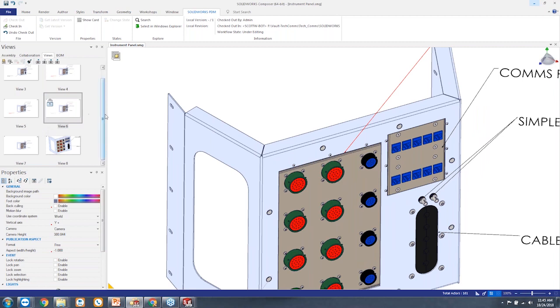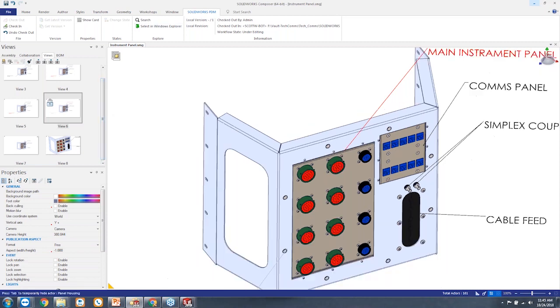But that view now is locked in stone, which is great, because let's say that you change all the colors and reposition things, set your neutral properties, and you're like, this is my view that I want to control after I do an update. Then you can lock it down, and that view will never change. It will change if you update, if it's tied to that update, but nobody can manually go in and change that view until it's unlocked. So really, really good addition there.